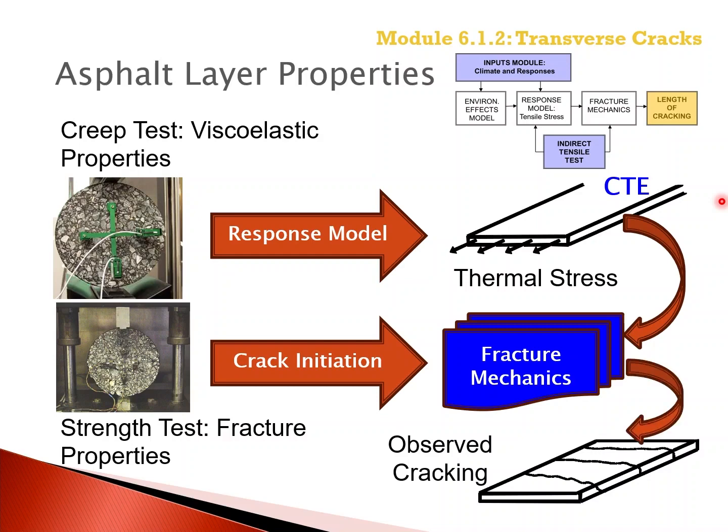The indirect tensile strength and creep compliance test are used with the fracture mechanics approach to calculate crack initiation and the length of transverse cracks over time.